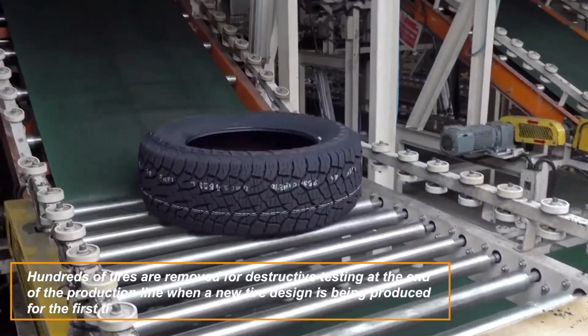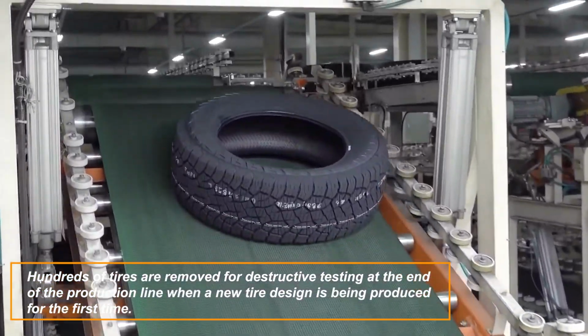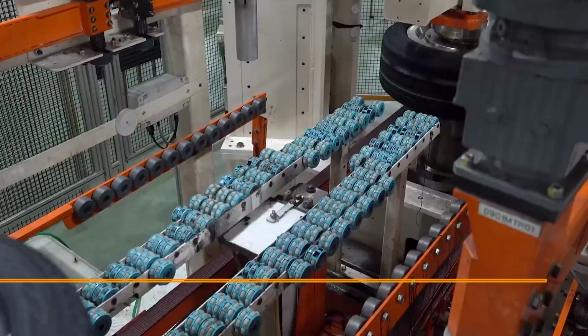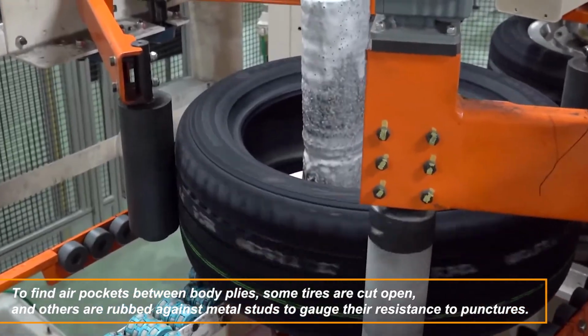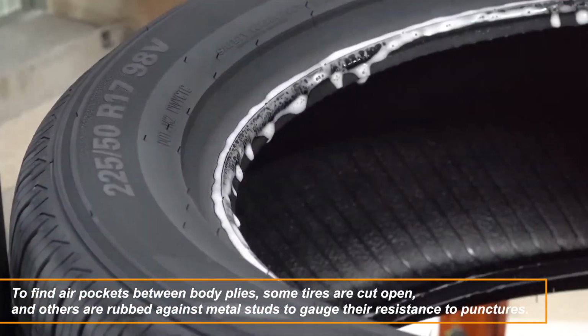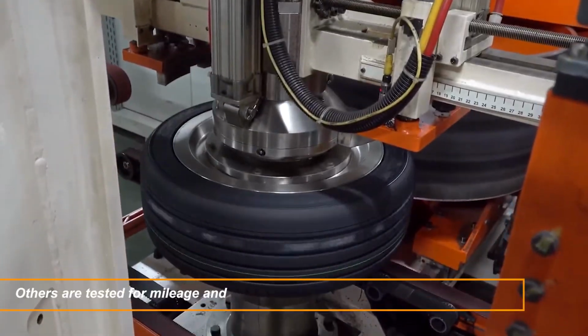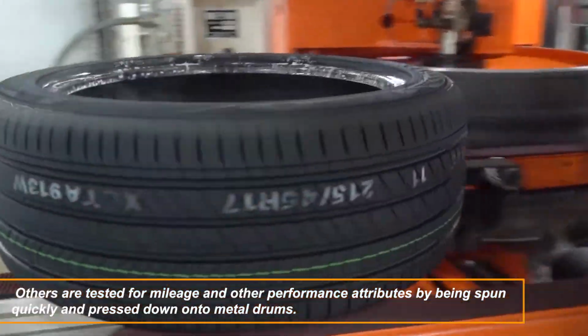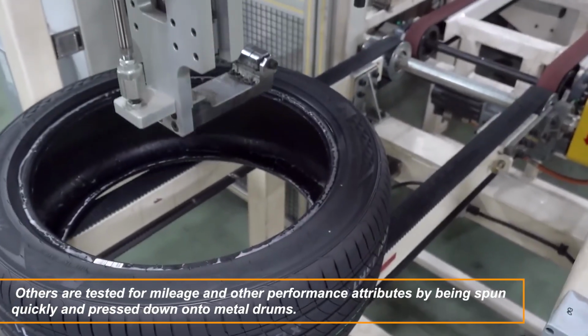Hundreds of tires are removed for destructive testing at the end of the production line when a new tire design is being produced for the first time. To find air pockets between body plies, some tires are cut open and others are rubbed against metal studs to gauge their resistance to punctures. Others are tested for mileage and other performance attributes by being spun quickly and pressed down onto metal drums.